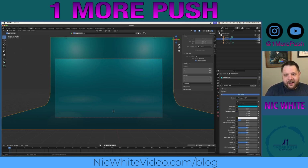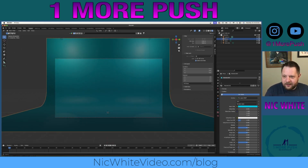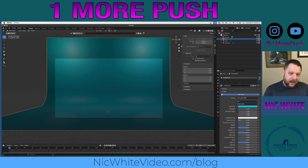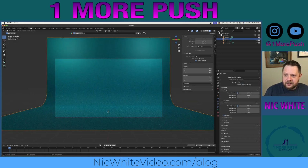So the color that you have now doesn't matter so much. It's more about the gradients and where the lights sit, and that's really what we're worried about at this point. So I'm going to turn the roughness up quite a lot, maybe 0.7, and let's change our render engine to Cycles, GPU if it's compatible.